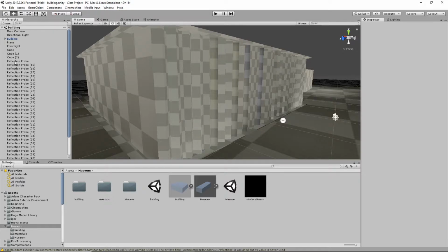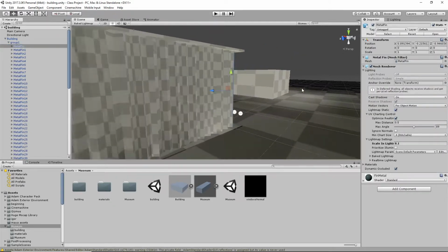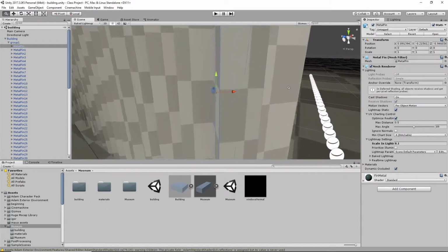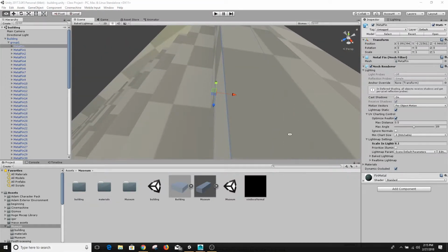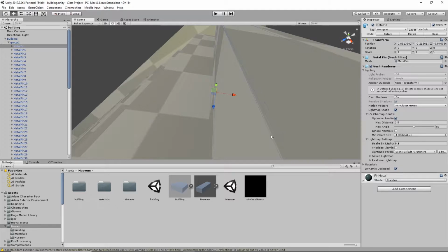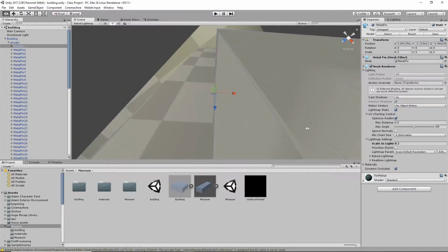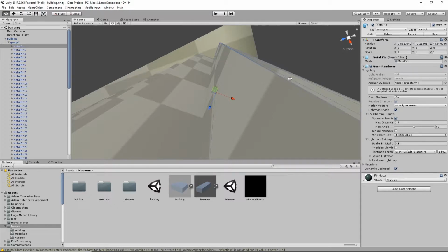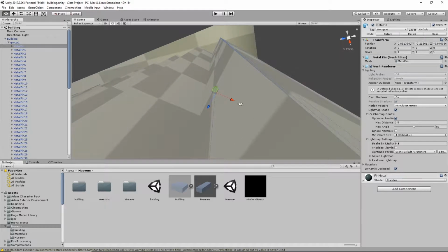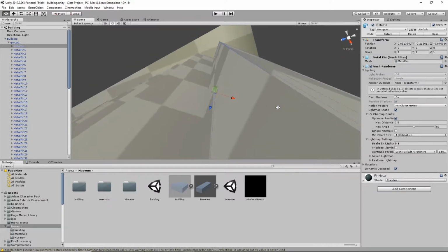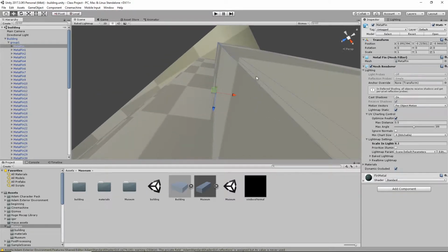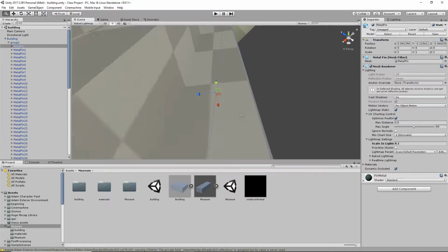So what I saw was, if I open up the building and the group, let's look at this first metal fin. If you hit F on the keyboard, you'll be able to see that these fins have a finite, small edge. These little squares here, based on the default mapping of cubes in Maya, were capturing a lot more texels of light than the bigger surfaces, or they were given an equal amount. So as big as this flat surface was, I was getting the exact same texel count on these inner surfaces, because they weren't UV mapped correctly.